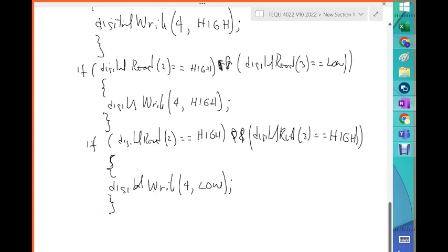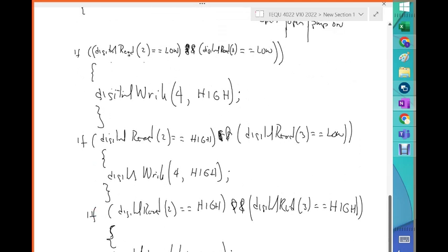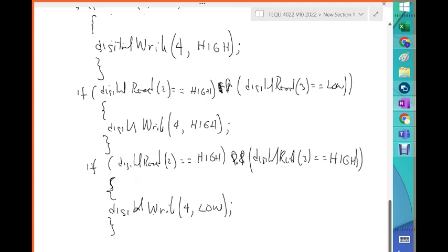All right, so up to there, we have the proper order of this. It's going up, so it's filling, and it makes sense. If both of the digital switches are in the low state, we're going to put the pump on. If the low level goes into high state, but the other one stays low, we still want the pump on. Now, when both are high, then the vessel is full, and we want to shut the pump. Perfect.